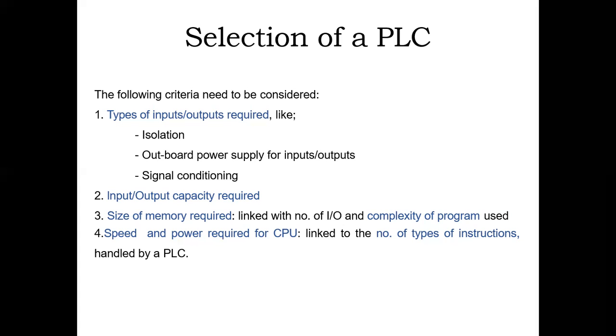So we need to define the input and output modules. Then the power supply requirements of the devices, because most input and output modules do not require 230 volts. If you use a 230 volt PLC, it will affect the system. So we need to define the power supply consumption, and consider that.